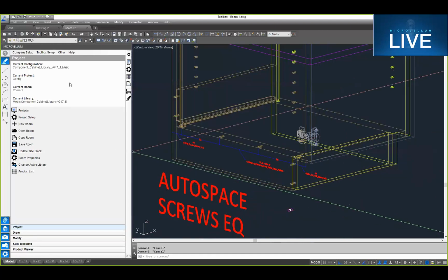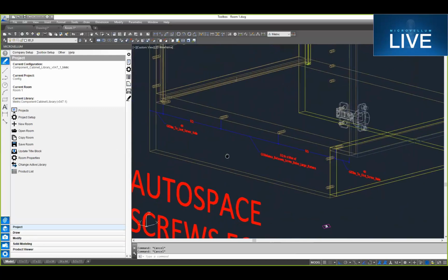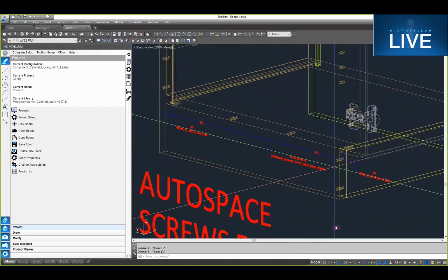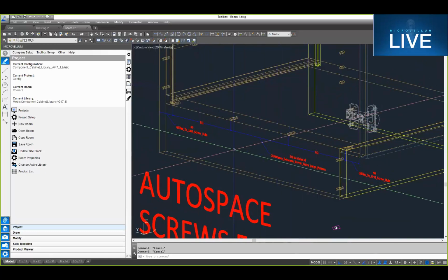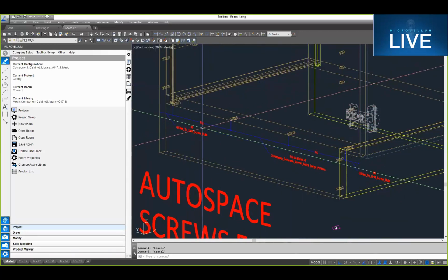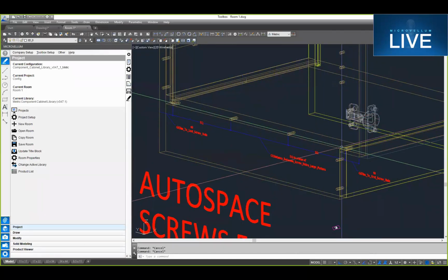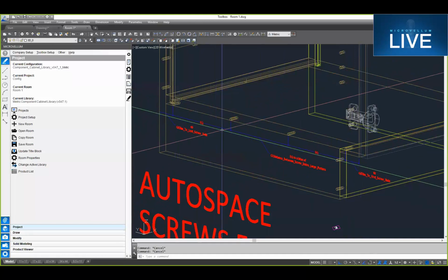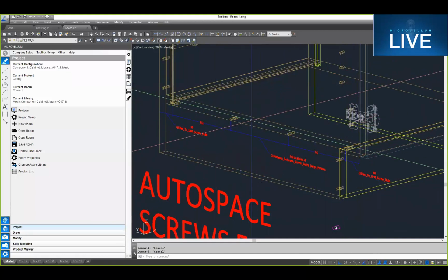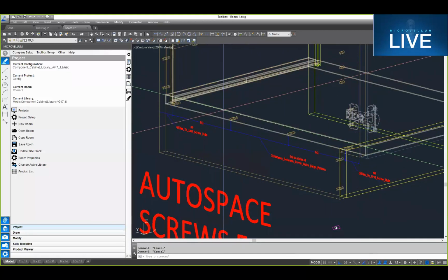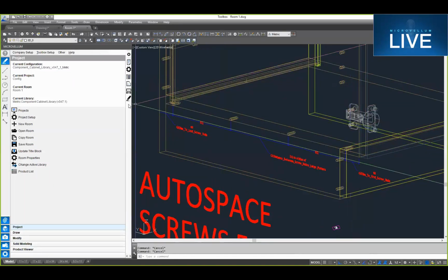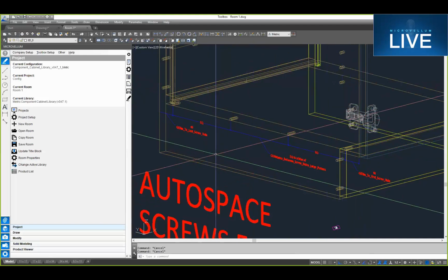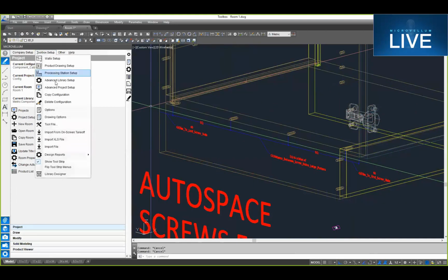Here, the way this one works is similar to our regular Autospace pattern, but rather than specifying exactly 128 for the first number of holes, we might just make all the spacing equal across. That works really well if you're drilling only in the vertical parts. You don't have to worry about the spacing of those holes matching up with a horizontal boring machine. Or if you just want to evenly space your dowels and you have a CNC boring machine, that's certainly an option as well.